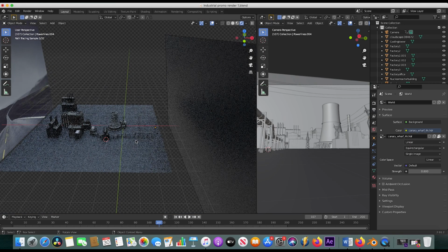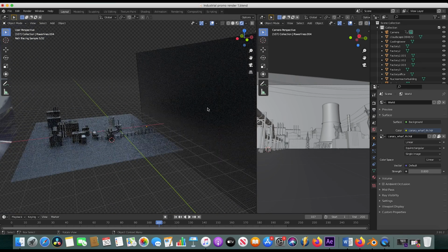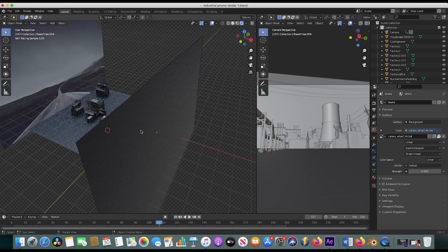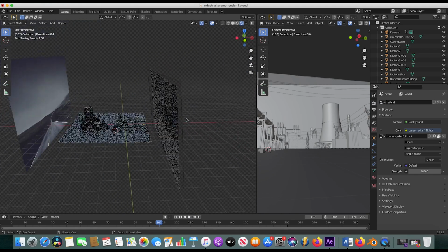Behind our camera here, we've added a black plane, and that's just to use as negative fill to create some shape on our assets. As I've mentioned in previous videos, negative fill is simply a technique where you block the light coming from the direction of the camera so that the scene and 3D assets have a little bit more depth to them. I'll put a link in the description on how to use this specific concept a little bit more effectively. But anyways, that's what we've done here.